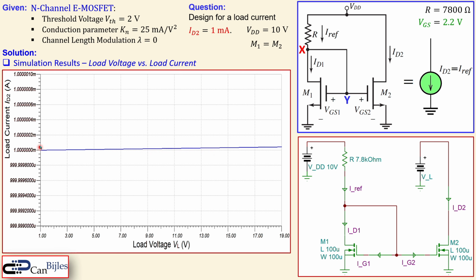Now, looking at the first here is 1.000002. So you can say there's almost no change here. That's the basic idea actually of a current source, because you don't want to have a huge change when this potential in your actual circuit is changing. We will see that later in other videos, that we will put this node directly, for example, to a differential pair to give the required tail current or for an amplifier. Now, you don't want to have a different current because that potential is changing. You just want to supply the constant current. That's actually the idea of this transistor configuration for the current source.